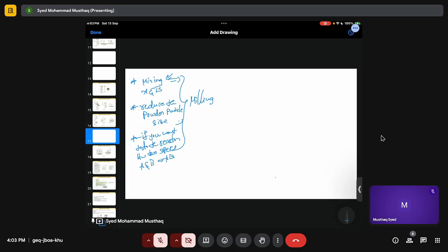So this energy is coming from the collision between the powder particles and balls. Now, if you do it at low RPM, the energy is not very large, it's small, so there is not even any breaking of powder particles. That's why we do the mixing at max 80 to 90 RPM, rotations per minute. If you have a planetary ball mill, sorry, not planetary, a high energy ball mill.